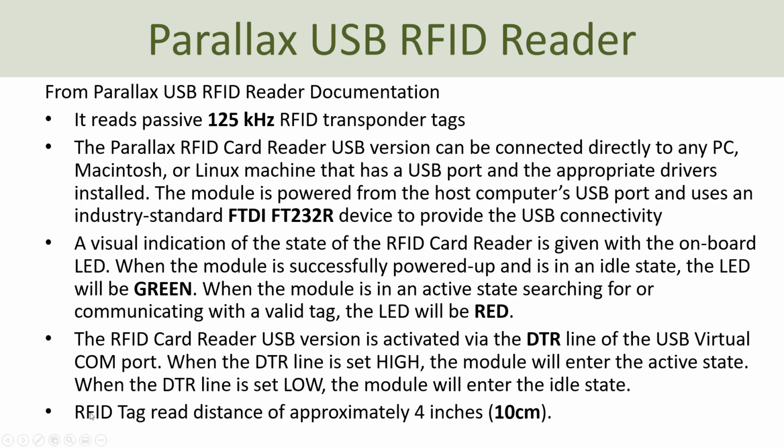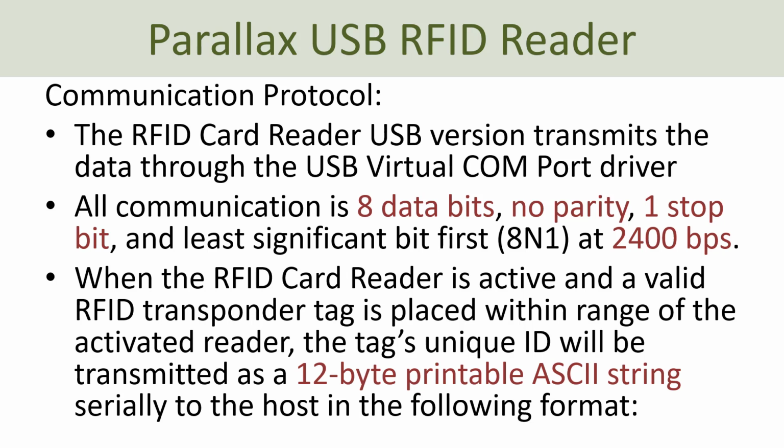This system has a short reading distance, so you need to put the tags no more than 10 centimeters from the reader and the built-in antenna of the system. Most RFID readers are based on serial communication, and the serial communication is through this USB cable and this virtual COM port driver, as mentioned earlier.